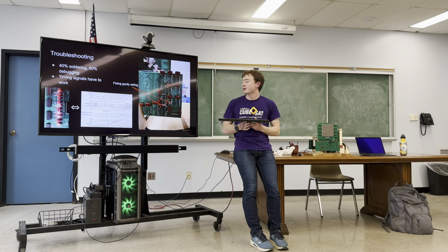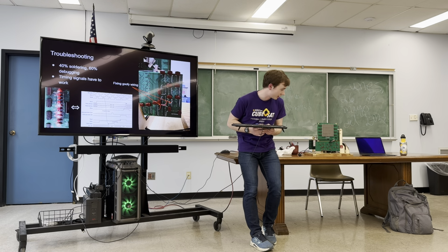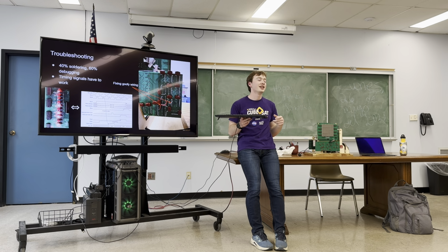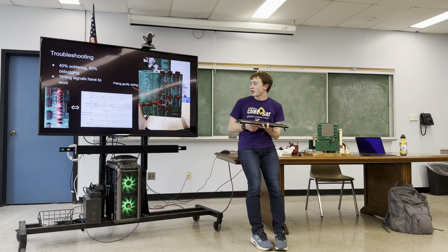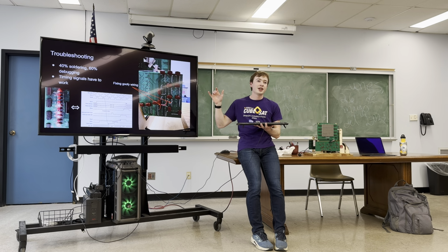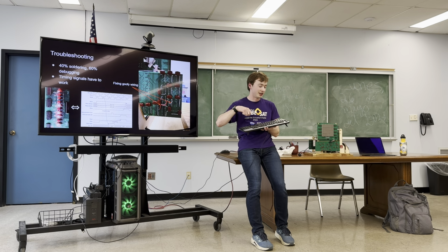Oh yeah, so this was most of what I did. I would put something together and then check that the timing would work, and it usually would. I messed up the outputs on a chip layout in KiCad, so it generated the traces the wrong way, so I had to take a pair of scissors and scrape it off the circuit board and then wire some other things, solder some other stuff on there.